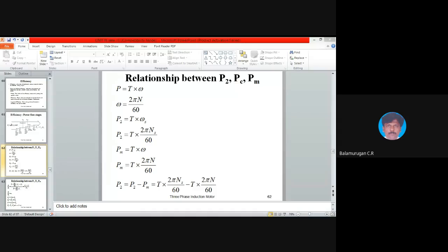Okay, you have to write all the parameters. In the open circuit test, what are the parameters we are calculating? I naught, R naught, X naught, I mu, I1, the core loss component. Everything will be calculated from that test only. In the short circuit test you will get the remaining parameters. If you wrote only the open circuit and short circuit tests, you will get only 3.5, 7 marks. If you wrote anything related to regulation and efficiency, you will get closer to 5 marks, 4.5. Okay, these are the problems.